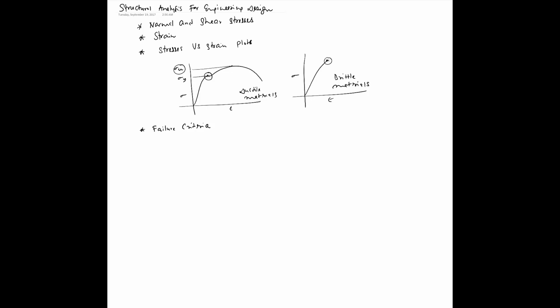Okay, so to give you a simple example, let's say I have a wire, and this wire is under tension, and that tension is given to you as, let's say, 300 Newton. And we know the diameter is, let's say 1 millimeter. Okay, so that's the diameter. So in this case, it's clear that at every cross section of this wire, we will have only tensile stresses defined as T divided by area.